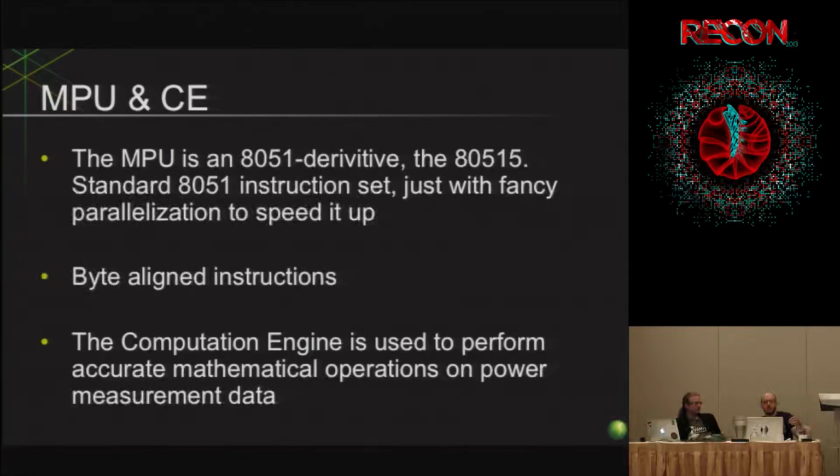But it shares access to X data as well. And if there are certain types of things that will block, and when you're in assembly and writing your own stuff, then you're not ever checking those types of things, and you won't even necessarily see that an interrupt occurred. So in general, we just turn all that stuff off if we're ever doing anything sensitive that we want to make sure doesn't get messed up. Like writing to flash would be one of those things.